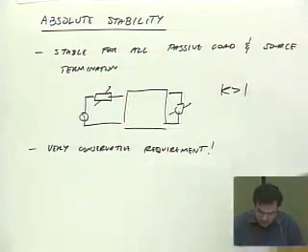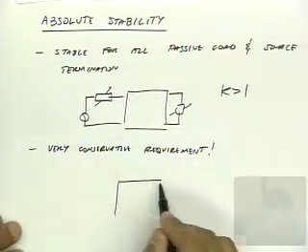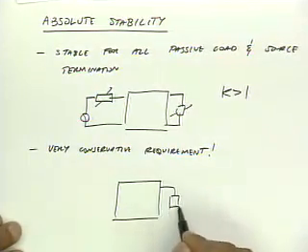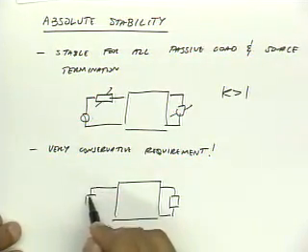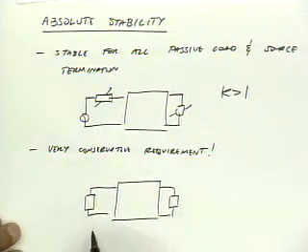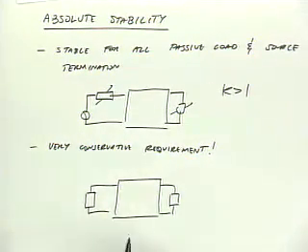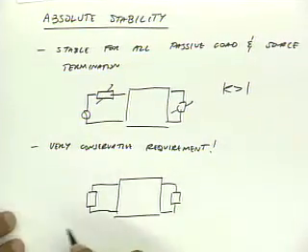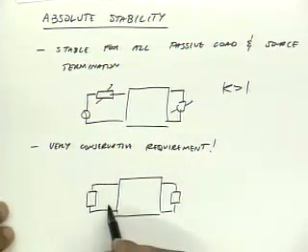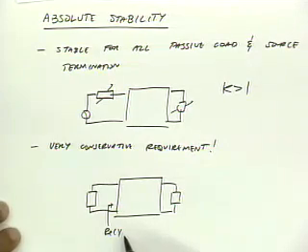Well, what's also interesting is if I have something that's not stable, so let's say I have a 2-port that's unstable, and I want to stabilize it. What's a really easy way to stabilize this 2-port so that I make it unconditionally stable? Exactly, add positive conductance. Remember, instability means that if I look into here, the real part of y in is less than 0.